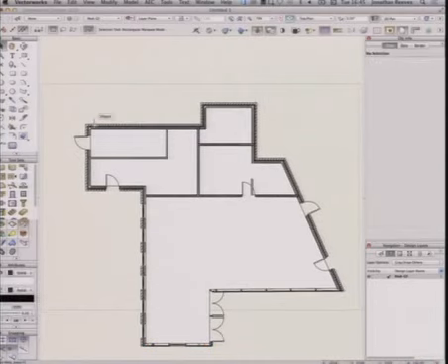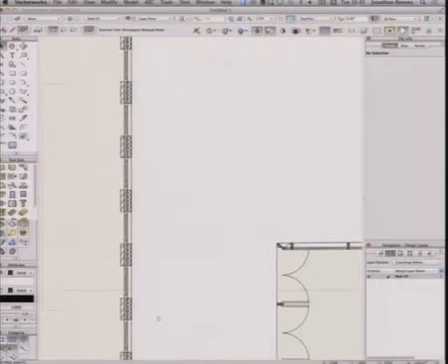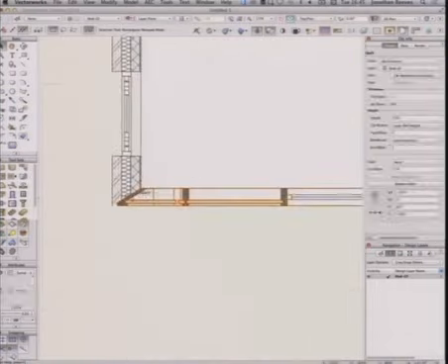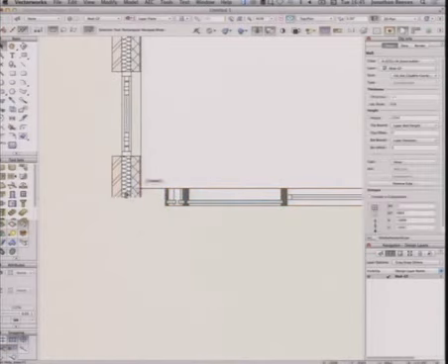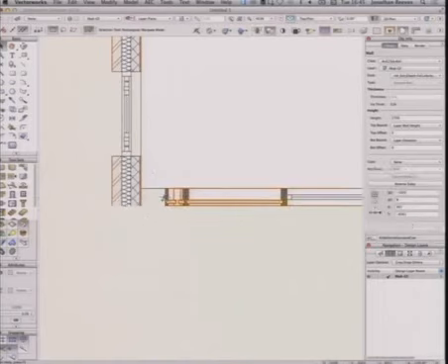Jonathan, could you just show how you repair the corners with your curtain wall beads, basically? Yeah, what I would actually do is I'd separate them. I wouldn't turn the auto-joining on. I'd probably extend that. I'd turn off the auto-join function, and I would literally just butt that junction up there.